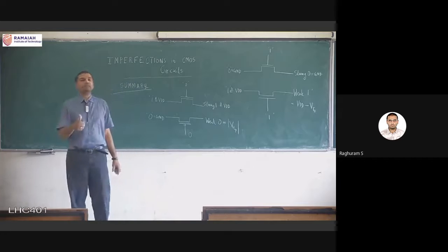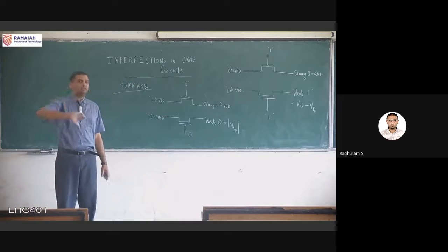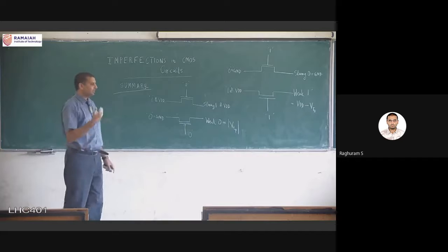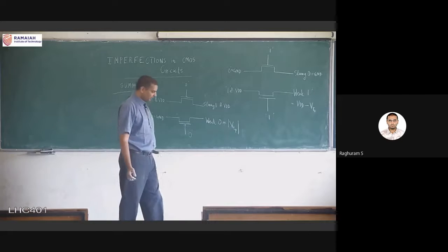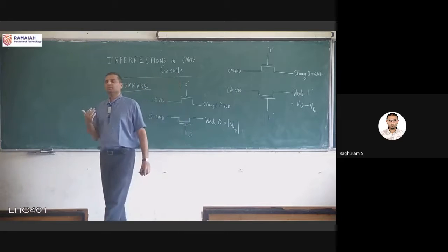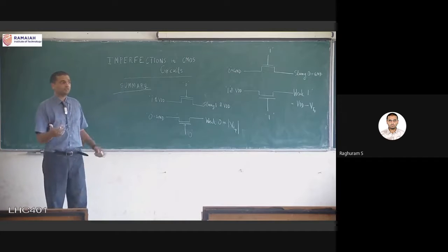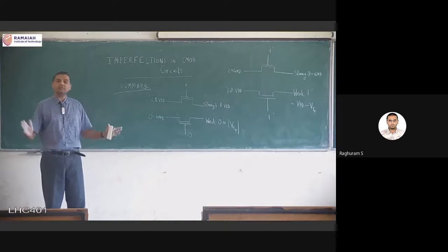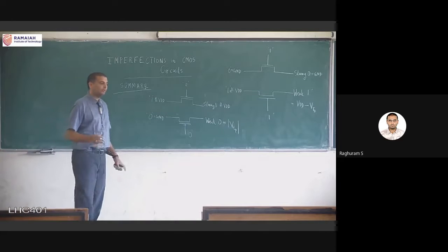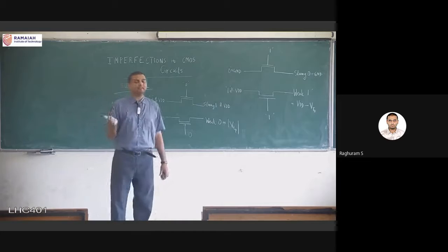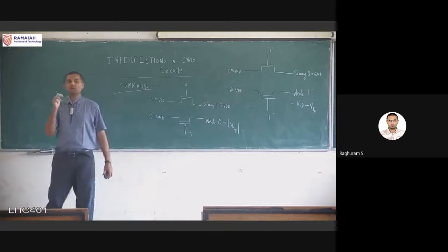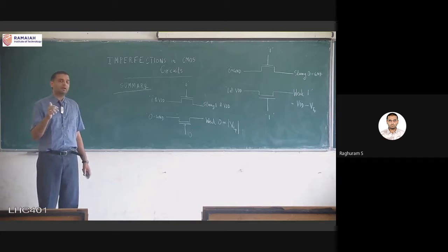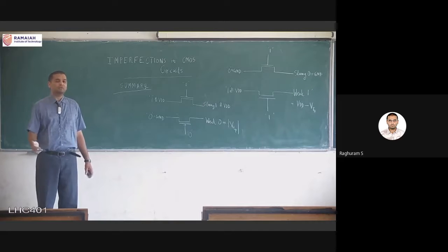Wherever the output is at a weak value, we don't want that, because as we will see later in this unit also, any output that is produced in our circuits, at least at the design level, we want those values to be at perfect levels. We don't ever want any circuit to produce values that are at imperfect levels. And this is one of the problems with the NMOS only or PMOS only technologies.